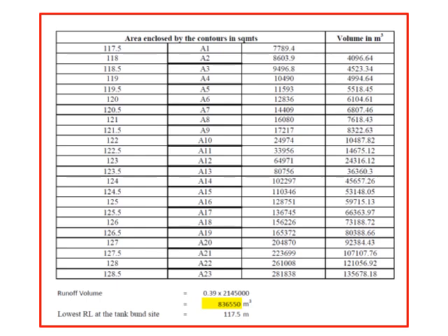Now the runoff, for this runoff volume you have to find out what the RL is. That will be shown in the next step. The particular level which corresponds to this volume, 8,36,550 meter cube, is the FRL. If you give 0.5 meters as the driving head for the surplus weir, you will get the maximum water level. Then you give a freeboard to the maximum water level, that will give the top of the bund. The top of the bund minus the lowest RL will give the height of the bund.